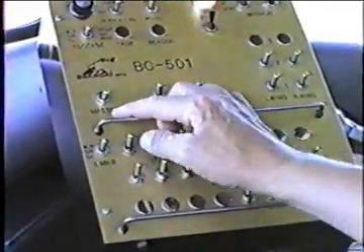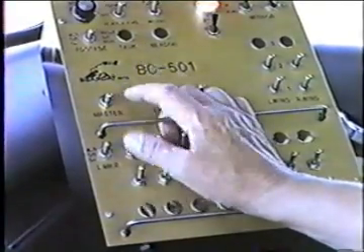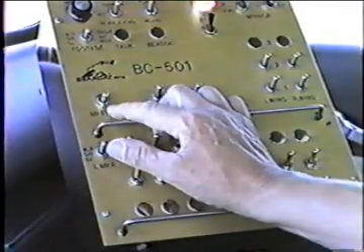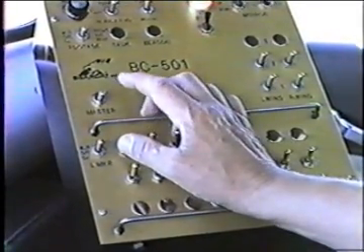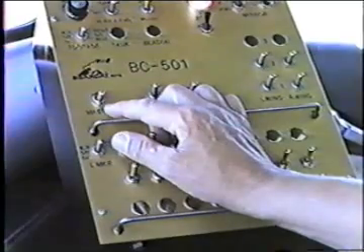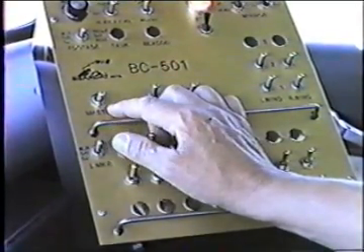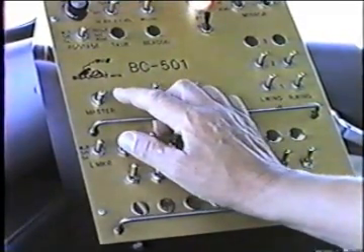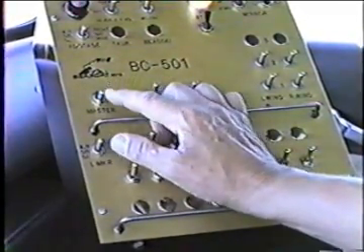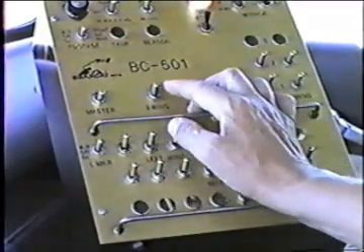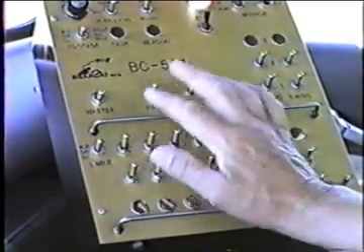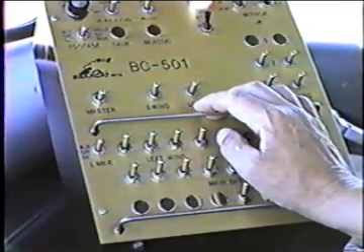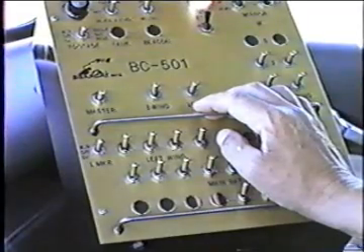Master switch. We've talked a lot about the master switch when we were back at the back end of the truck, with a lot of discussions about when the master's on and when it's off. Well, this is the spray bar master switch. What it does is it turns on whatever spray bar that we have pre-selected as far as width, as well as it'll turn on the footage meter, and it'll turn on the computer when we're in computerized spread rate control. Anytime the master switch is off, all those functions are turned off if they're in the master position, and the computer goes into the idle mode.